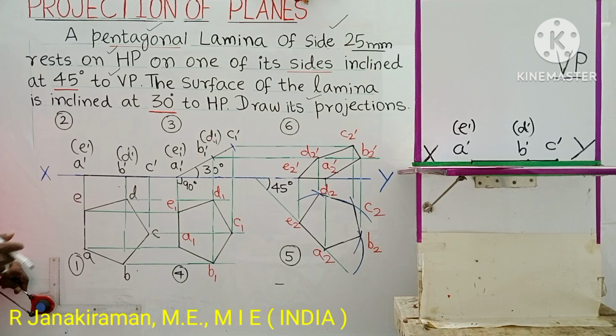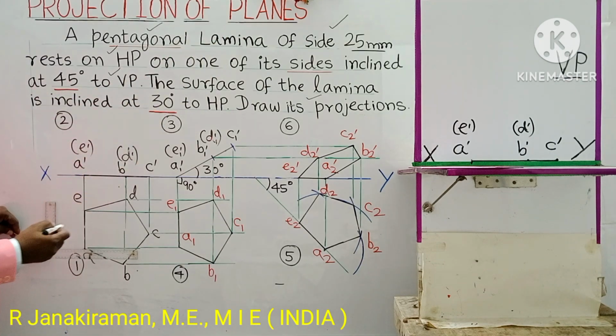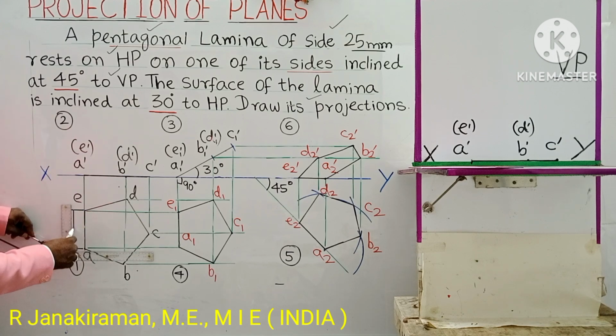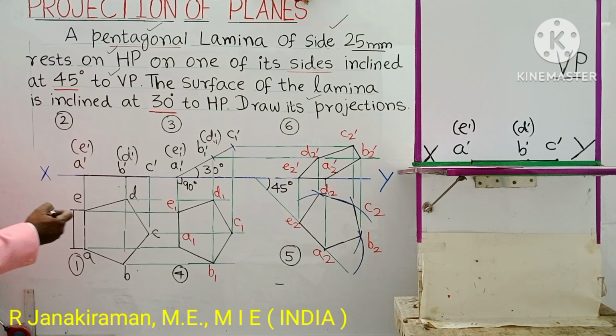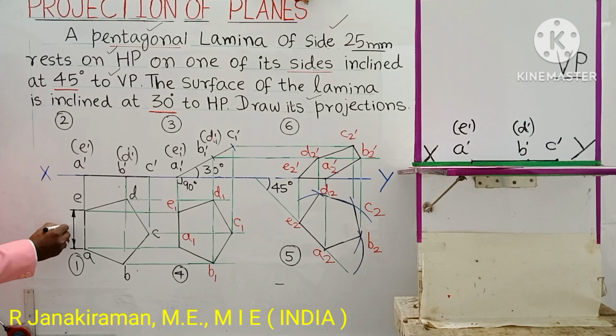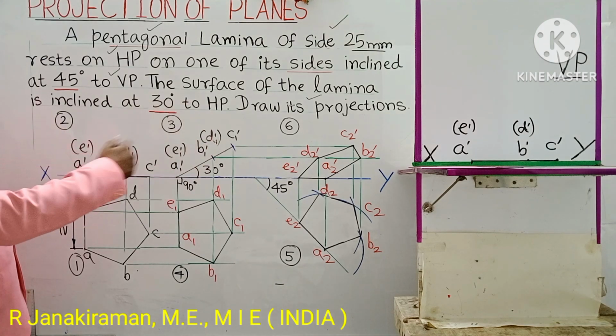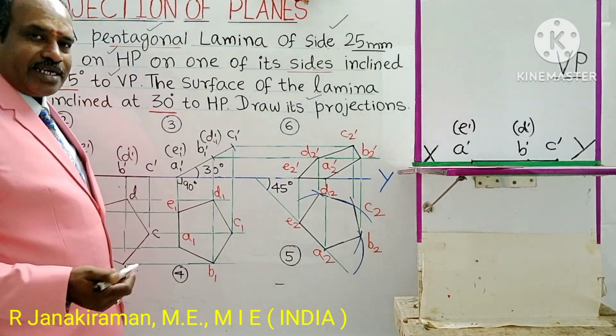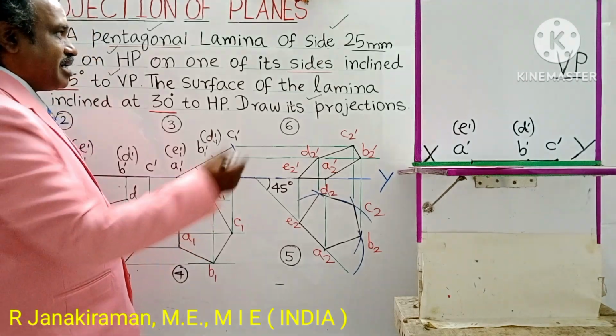Dimensioning carries marks. The size of the pentagon is given as 25 mm. From A, draw an extension line using the longer scale of your drafter. Similarly, from E, draw an extension line. Then draw a dimension line using the vertical scale of your drafter, parallel to AE. Put two narrow arrowheads, shade the arrowheads, and write the side as 25 in terms of millimeter. After completing this diagram, draw two guidelines using a longer scale of a drafter, and write all dimensions are in mm. Mm means millimeter is the unit followed.